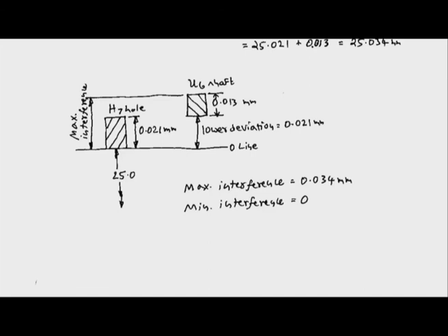Now we have taken examples of different basic sizes like 25 mm, 50 mm, 60 mm, and then we have considered the basic hole H with different IT grades like IT7 and IT8, and also we have taken different shafts, M shaft, D shaft, P shaft, S shaft, U shaft with different tolerance grades of 7, 6, 9 etc.